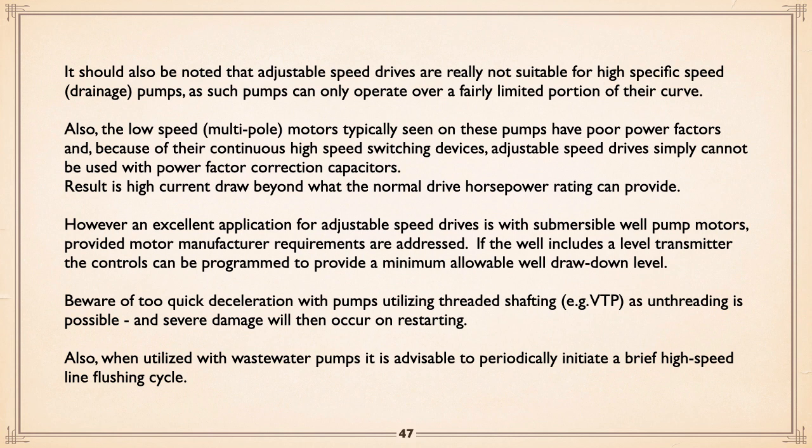Another little trick: the low speed motors used on those pumps have poor power factors. And because adjustable speed drives, as with solid state starters, simply cannot be used with power factor correction capacitors, if you try to use them on a drainage pump, you'll find that their very poor power factor cannot be corrected. So you end up with a very high current draw beyond what the normal drive horsepower rating could provide. In other words, if you can put capacitors on, you'd be much further ahead than by using variable speed, which prevents you from using capacitors.